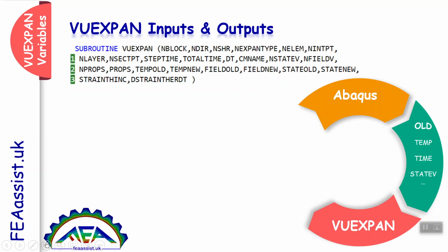In VUEXPAND, we need to process these variables and compute new variables like the thermal strain increment and state variables, and return these outputs back to Abaqus.